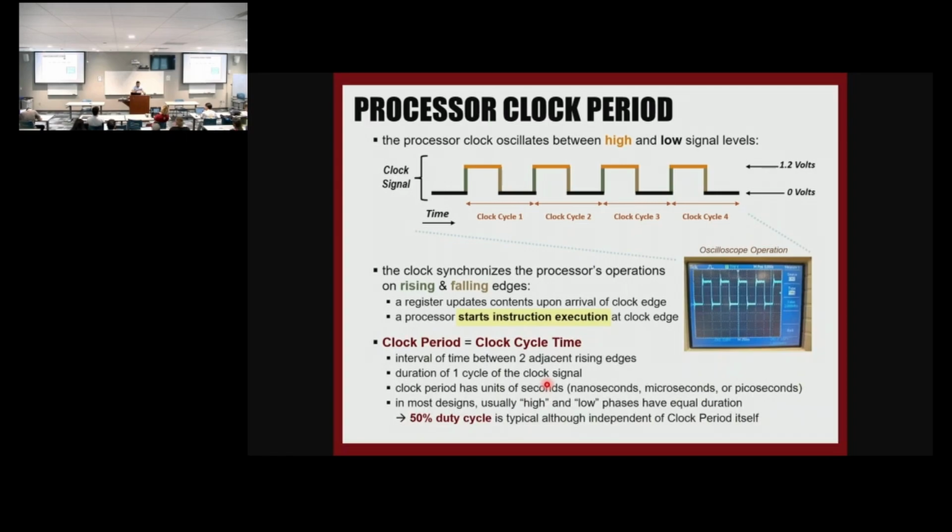Asynchronous design is a big thing by itself, so we can't oversimplify it just because you're asking the question. I just mentioned something, but asynchronous design is beyond just working with clocks. Sometimes with clocks, you always do something at the clock. Asynchronous design involves something like handshaking, for example, where you don't really work with a clock, you wait for the other part of the circuit to complete its task. So it's a little bit more complicated than just playing with the edges of the clock.